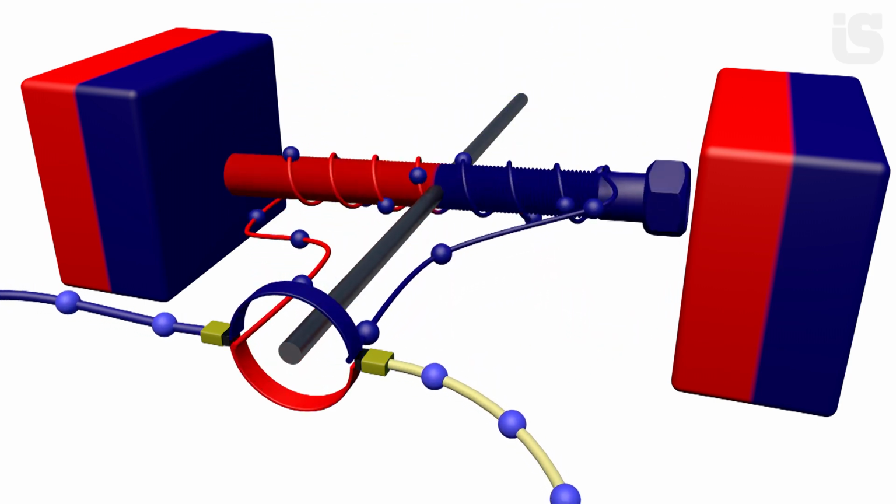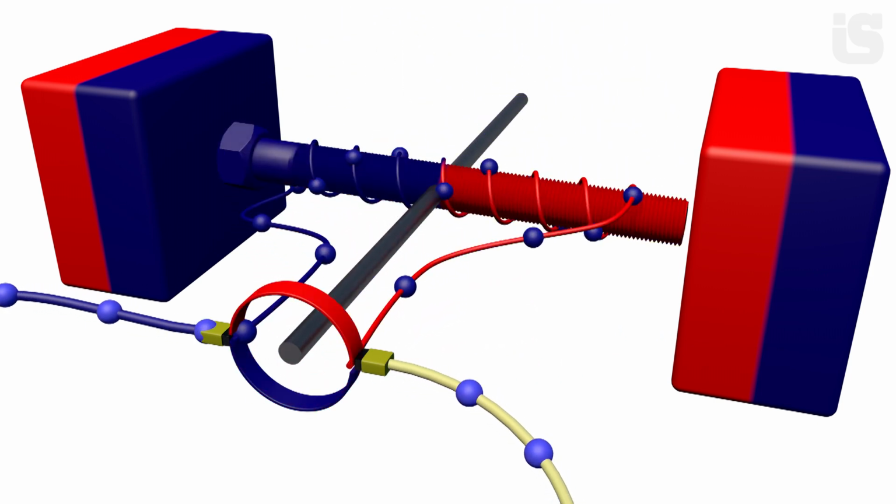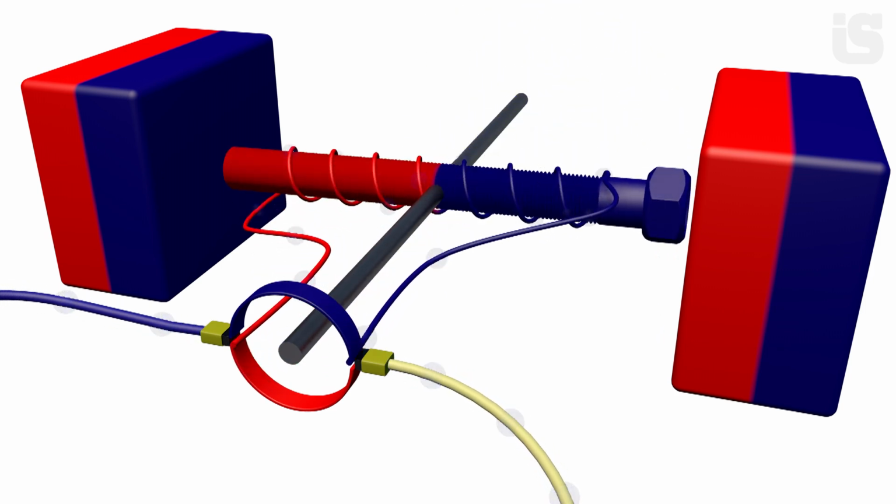As the armature rotates, each segment of the slotted ring comes into contact with one brush. But when the armature turns completely under the influence of the fields, the segments of the slotted ring will come into contact with the opposite brushes. The electric current in the armature winding will reverse direction and the poles of the electromagnet will switch places.